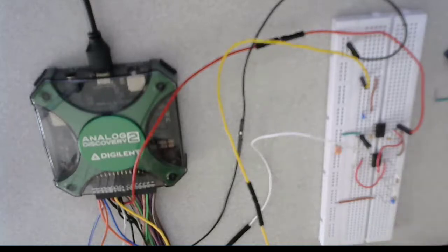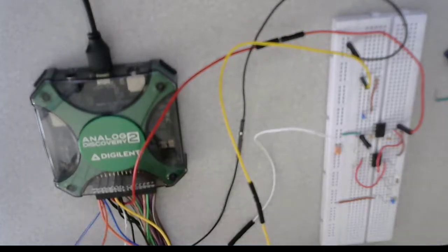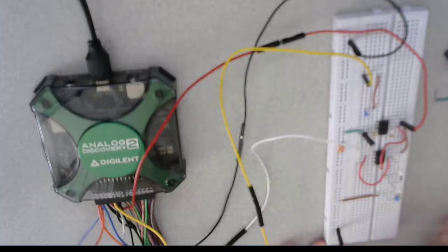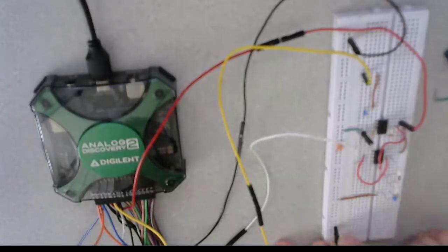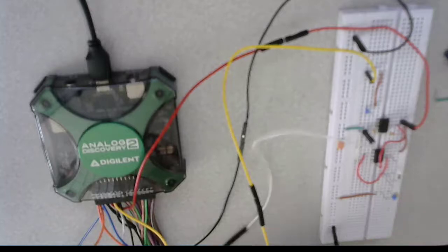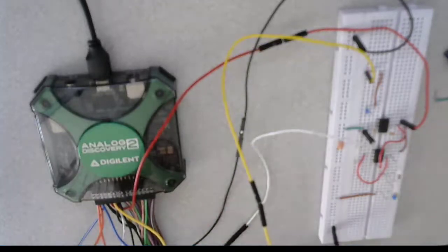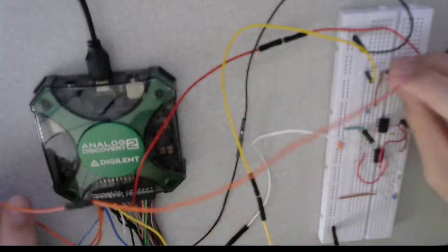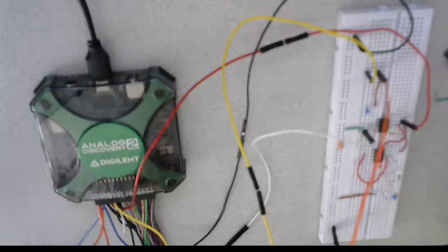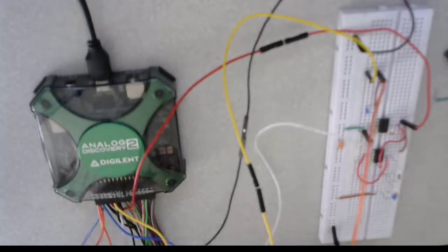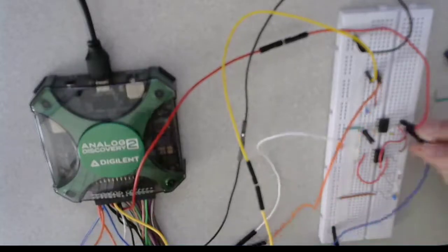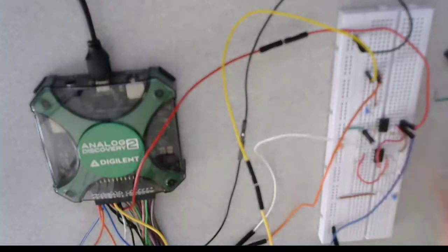Now we can set up our channel 1 and channel 2 measurements. I'm going to connect both the scope channel 1 negative and scope channel 2 negative cables directly to the ground rail. These are labeled 1 minus and 2 minus on your AD2. Next, I'm going to connect the scope channel 1 positive cable, which is solid orange and labeled 1 plus, to the input node of our differentiator circuit. And I will connect the scope channel 2 positive cable, which is labeled 2 plus on your AD2 and is solid blue, directly to the output of the differentiator.